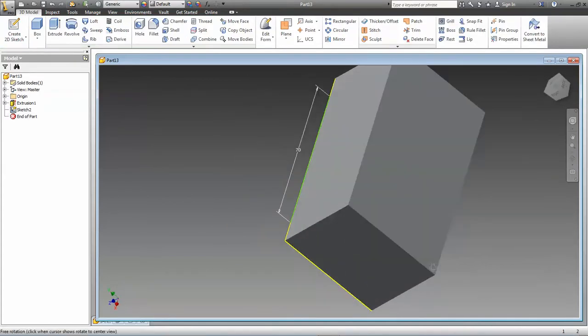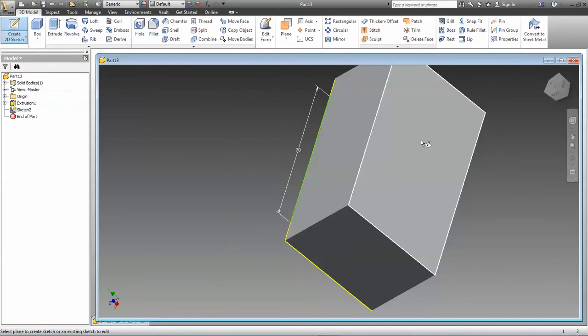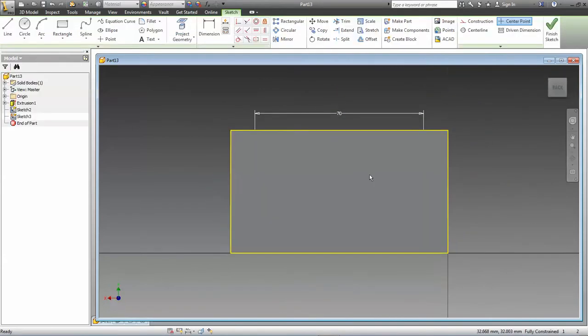Need to go back around here, create a second sketch with a triangle on the back. Again, we need a work point for that lower vertex of the triangle. And this one, I believe, is at the center at 30 millimeters from the bottom. But again, don't use my dimensions. You should have already done your multi-view drawings of all these parts. So go by your dimensions, because I may make a mistake here. I'm just going by memory.